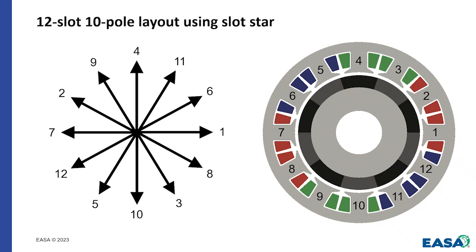And what we have is a depleted battery in my pointer. But what we have is, we had number 3, which was right here. If we go another 150 degrees, we end up with number 4 here. Another 150 degrees, we get to 5. Another 150 degrees, we get to 6. So we just keep repeating that pattern until we go all the way around through 12. And what we end up with is an arrow that represents every coil. But if you look at the number that's assigned in the layout of the arrows, it's not real logical about the best place to energize.